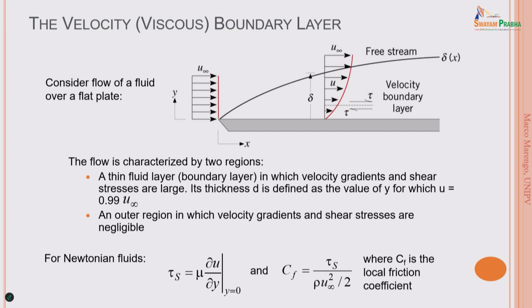The viscous boundary layer is defined as the position in space, let's say normal to a surface. The surface can be in any position. We go normal to the surface, and we capture the point where the velocity is 99% of the undisturbed velocity, the one that came from a direction and was changed because in contact with the wall the velocity becomes 0.